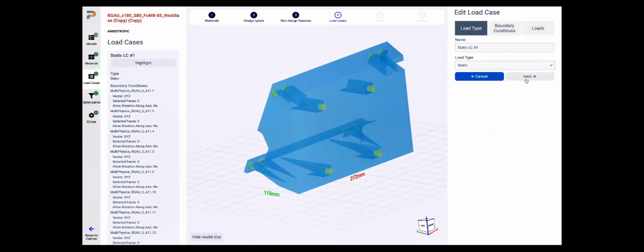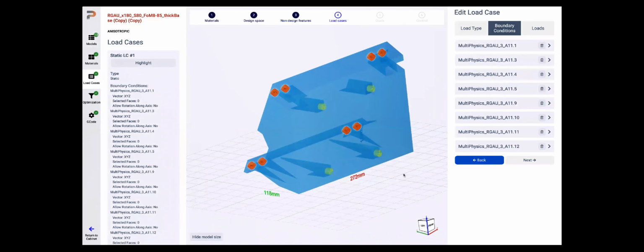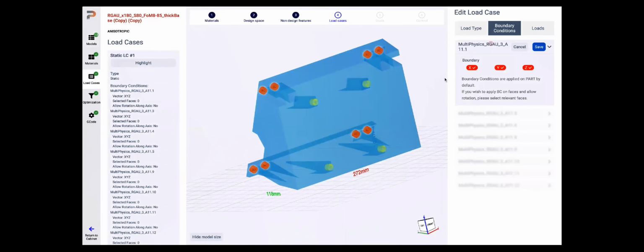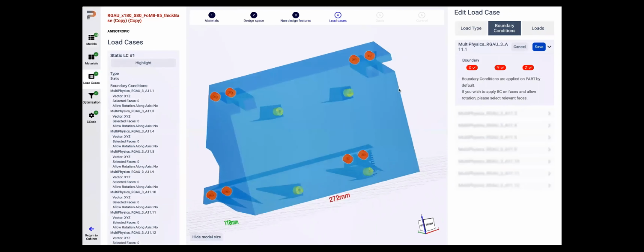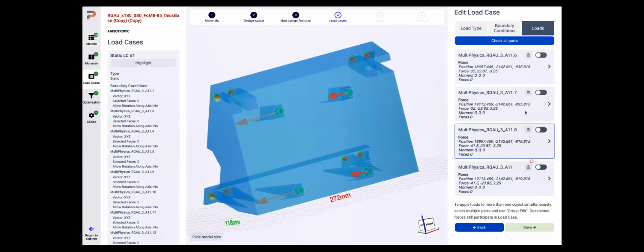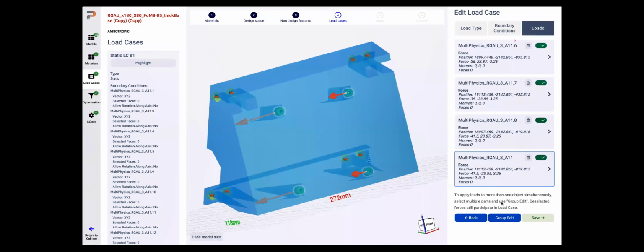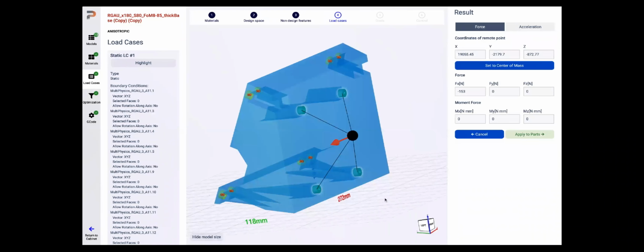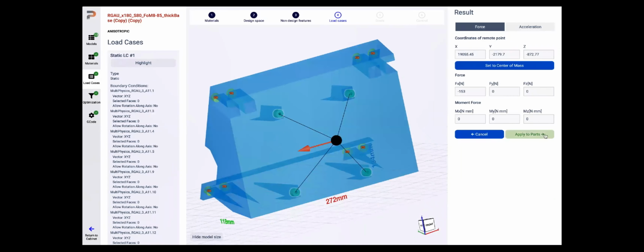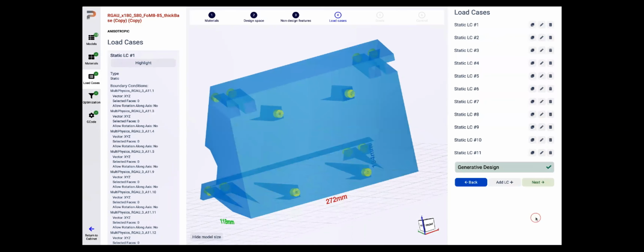We support a variety of loading conditions, static and vibration load cases. So for statics, we need to define the boundary conditions, how the part is fixed against movement in various directions. Second, we apply loads, and as I mentioned, there is a variety of loads. Can be forces, moments, pressure, acceleration loads.